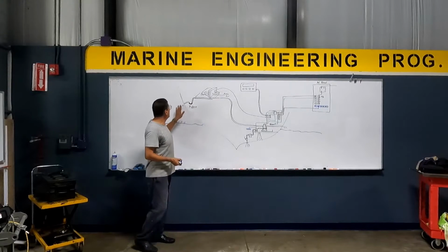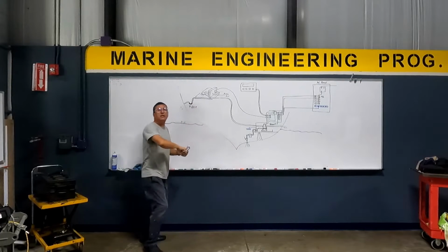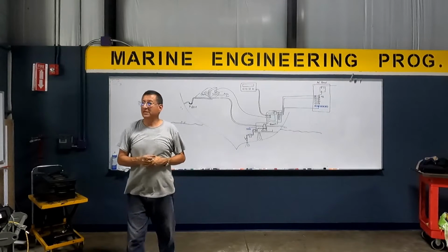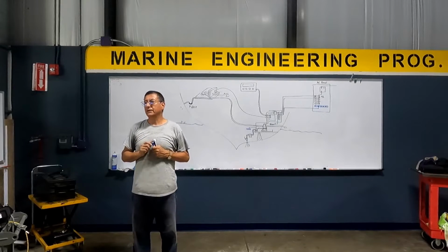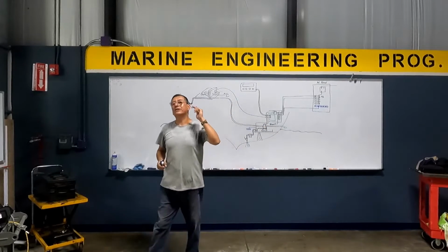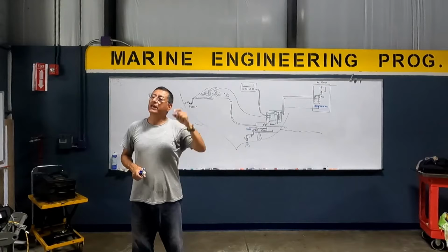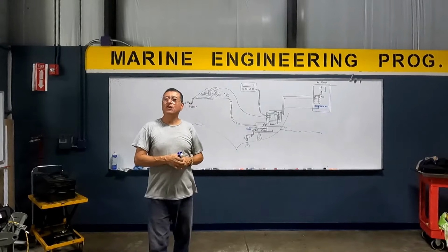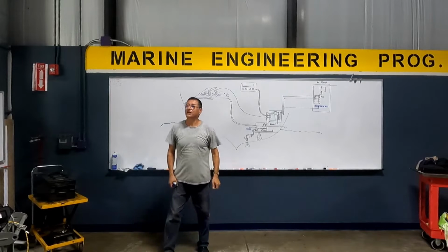In some boats, this one could be sent directly into the bilge and removed with the bilge pump. If the boat is a wooden sailboat, that is not recommended. It's better outboard. It's okay, guys? It sucks water in. It's clear? This one is salt water from the condenser unit, and this is the water that you see in the boats, in the marinas, going out constantly. It's because the air conditioner is running. If the air conditioner is running, the raw water pump should be running constantly.